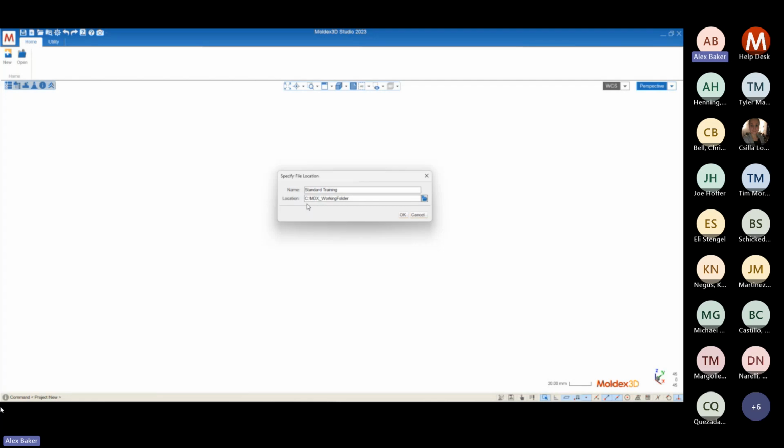If you put your files on an external hard drive or a thumb drive or a network drive or a shared drive, whatever, you have to keep in mind that wherever the files are stored, there has to be a communication with your local drive where the solvers are located. That communication can be delayed if there's a network connection or any sort of external connection, and at the best case scenario, it will cause your simulations to bog down and your computation time will be longer than necessary.